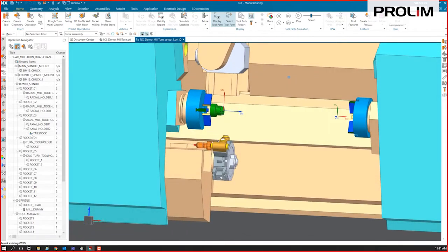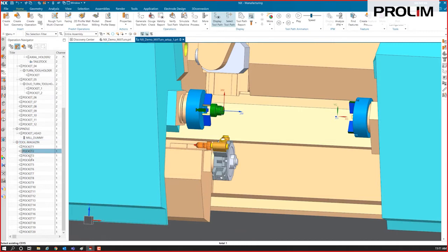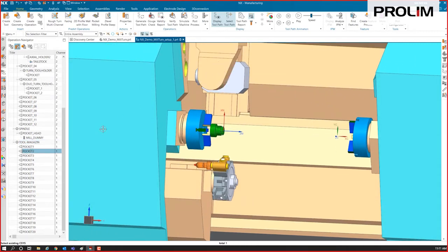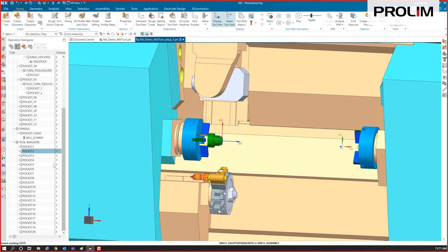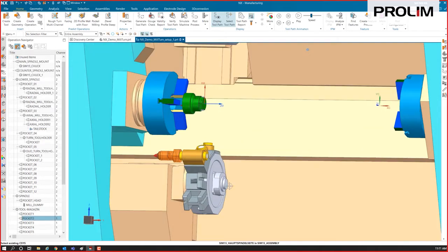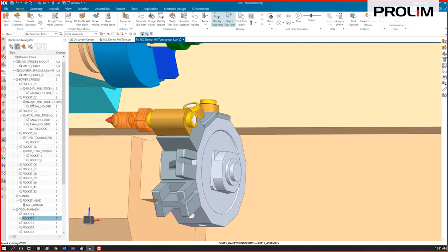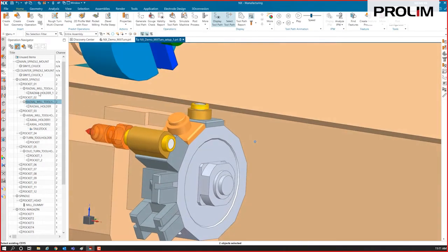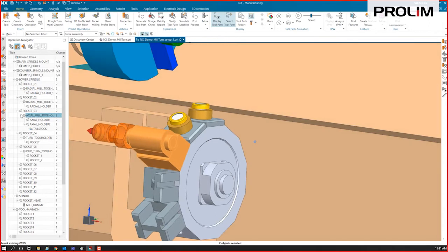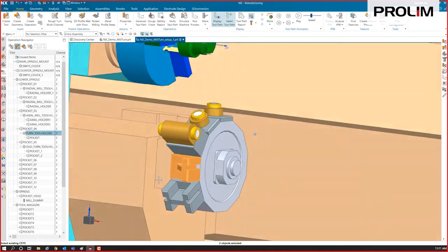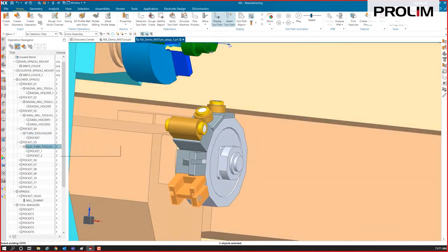So in here, these are all the different tool magazine pockets we put tools inside of for this upper head to grab the tools out of, or even on this lower turret, we've got different pockets and different tool holders down here, such as this radial mill holder here. Here's another radial mill holder. We've got this axial mill holder with a couple of different pockets. You can put it on the front or the back. We've got this little tailstock. We're not really going to use this tailstock, so I can just delete that out. We can get rid of that. A turning holder, this duo holder.